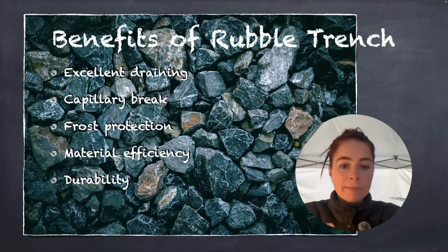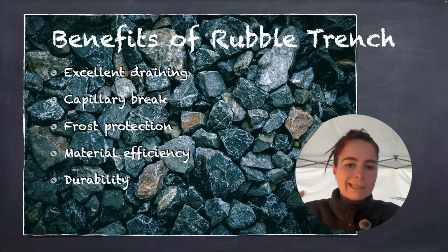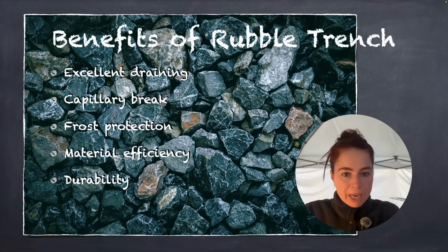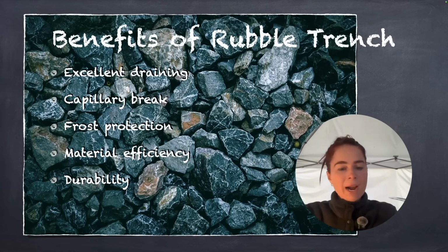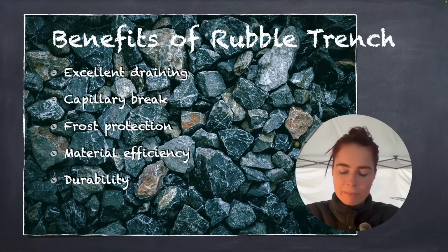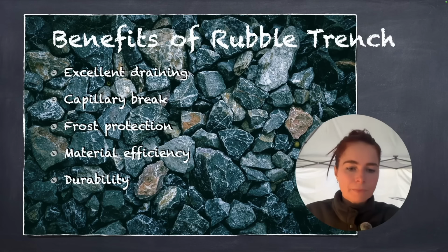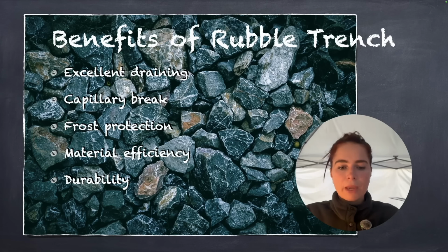And it's a capillary break, so it does not wick water the way that concrete does. It doesn't act like a sponge because it has those big pores, not those little pores. So that rising damp phenomenon doesn't even happen. Super cool. The other thing is it provides frost protection. So the water is going to drain out before it can freeze. So frost without water has no power, goes the saying. It cuts the water supply off that will even cause frost heave.